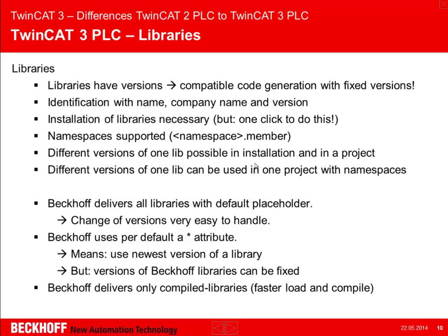So placeholders are really making life easier for version handling with a set of libraries, with your own libraries and Beckhoff libraries. We deliver our libraries with standard placeholders. This means the placeholder name is similar to the name of the library, which is easier to find. Of course, you can rename this, and of course, you can also set placeholders in the next version for your own libraries.